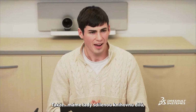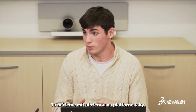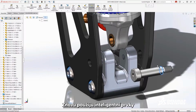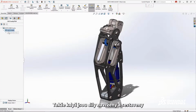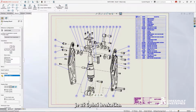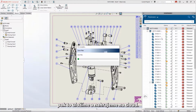So we have that shared component library that everyone's supposed to be using, right? We can store that on the platform too. I'll search for a shoulder M6 screw that's 25 millimeters long. I'll use SmartMates again to put the screw into place. So now the parts are designed and assembled, let's make a quick exploded view. And a quick drawing out of this thing is super easy. We can even add a bill of materials and then save it and upload to the cloud.